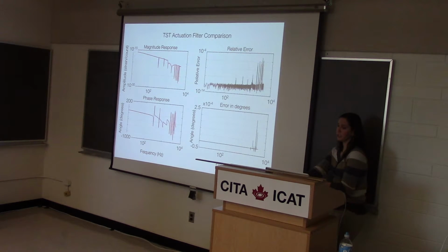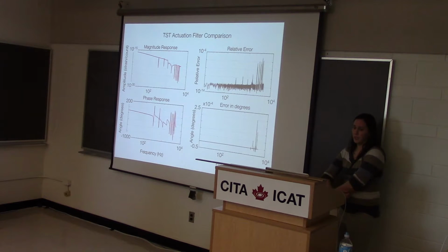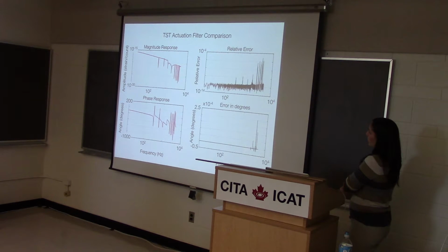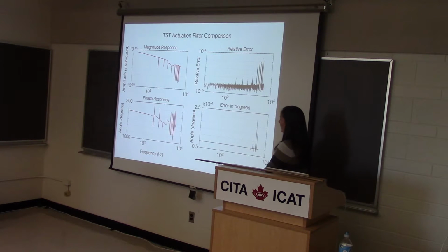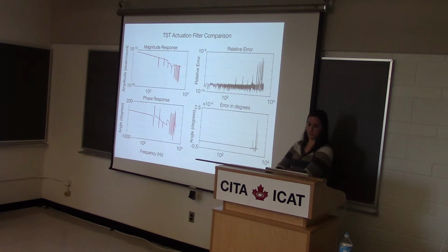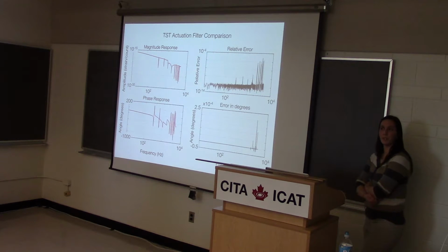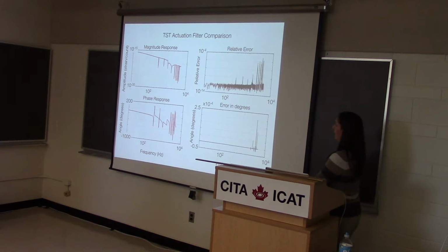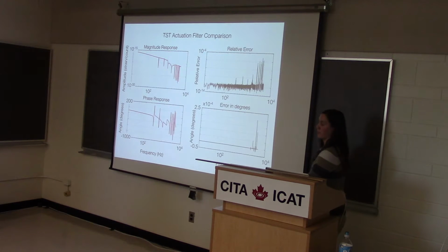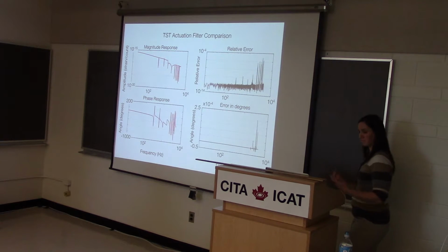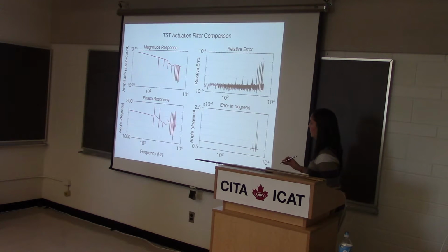So what I'm going to show here is just the results of taking our frequency domain models, computing an FIR filter with them, and then what I'm showing is just a comparison of the frequency response of that FIR filter to the true answer, the frequency domain model that it was based on. And you can see we've got a technique that gives us very good accuracy for the FIR filters in terms of their faithfulness to the original frequency response.